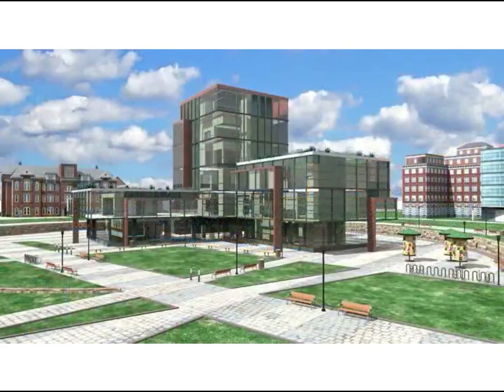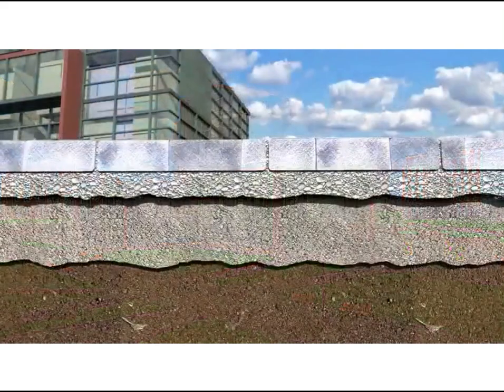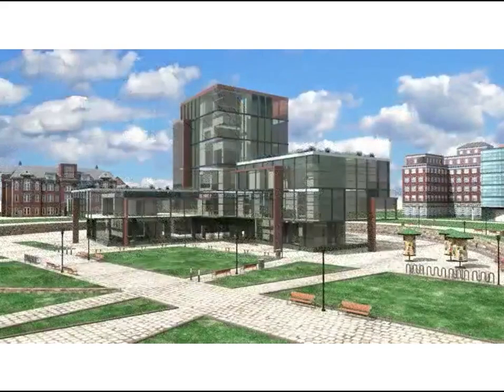Concrete surfaces are replaced with individual concrete bricks called pavers. Each paver is interlocked with its neighbor and separated by permeable material. The permeable material is composed of small crushed rocks, also called aggregates. Zooming into the cross-section, we see the permeable aggregates between and below the pavers. The aggregate-filled space acts as a sponge, absorbing water downward, diverting a good amount of runoff from the storm drains. The diverted water will eventually make its way into the aquifer below ground.